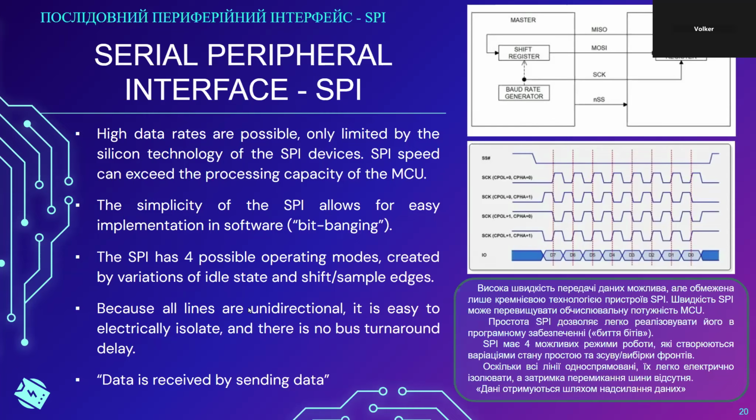So now you have the problem you want to interface, for example, an SPI EEPROM or an SPI storage, otherwise storage device. And what you can do relatively easily, you can just take 4 random port pins, GPIO pins on the microcontroller, and you can implement an SPI interface in software.